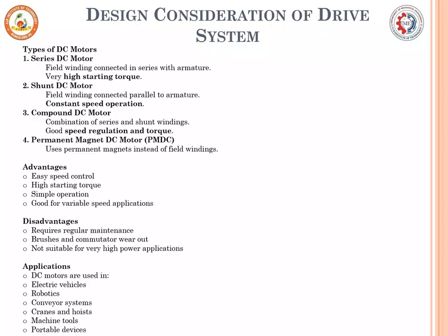Its disadvantages are that it requires regular maintenance, as brushes and commutators wear out, and it is not suitable for very high power applications. The applications where DC motors are used include electric vehicles, robotics, conveyor systems, cranes and hoists, machine tools, and portable devices.